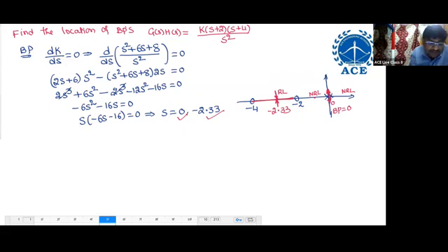Number of asymptotes, you tell. Number of root locus branches is 2. The number of asymptotes you will automatically get. Number of root locus branches means what? Either poles may be greater than 0 or poles may be less than 0. Here poles equal zeros, that means same, equal to 2. Number of root locus branches is 2. So number of asymptotes is 0. Whenever asymptotes are 0, angle of asymptotes and centroid not required.